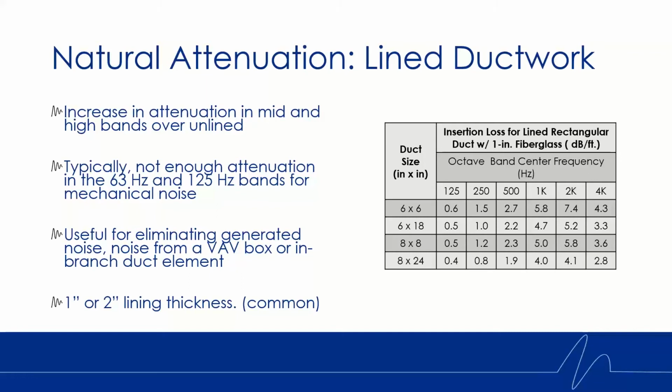Lined ductwork is really effective when used with an in-branch duct element like a VAV box, something a little bit smaller, where a lot of the sound energy is going to be in the mid or higher frequencies.